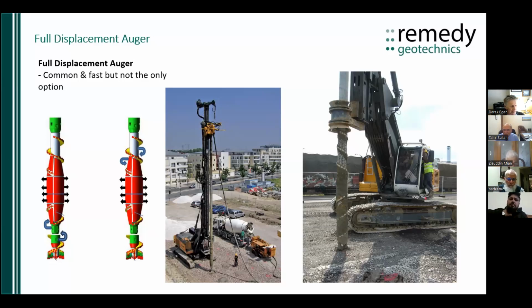It's going to be more than 1,000 times different. As some people do, they market their columns. There's one company that calls their columns controlled modulus columns, indicating they use a weak concrete, which has a lower stiffness than a normal concrete. But I don't think it makes much difference to the design. But technically, you're correct. Difference in stiffness is relevant.